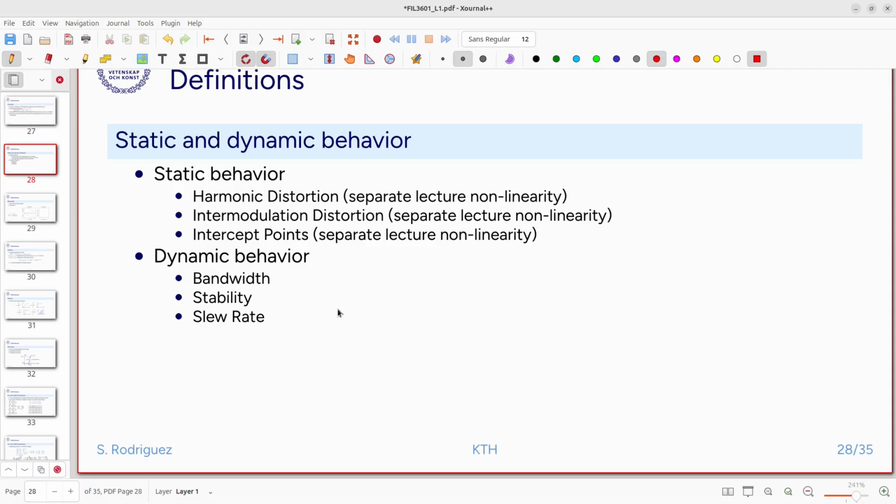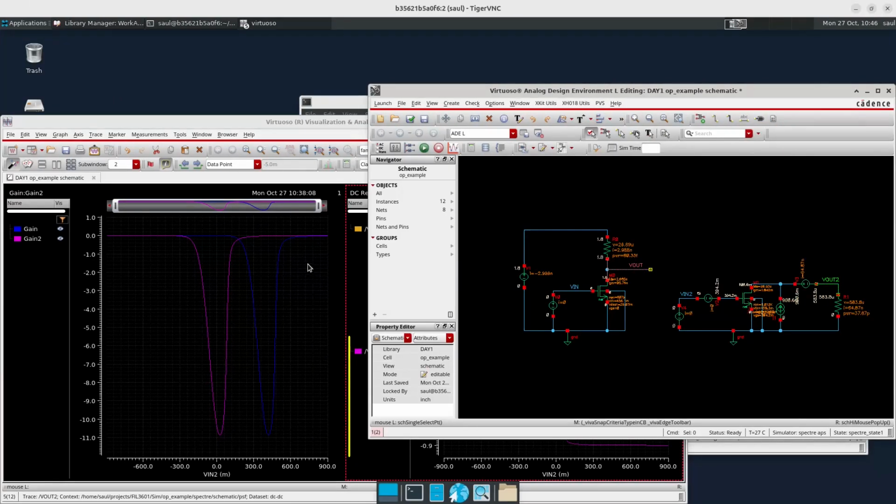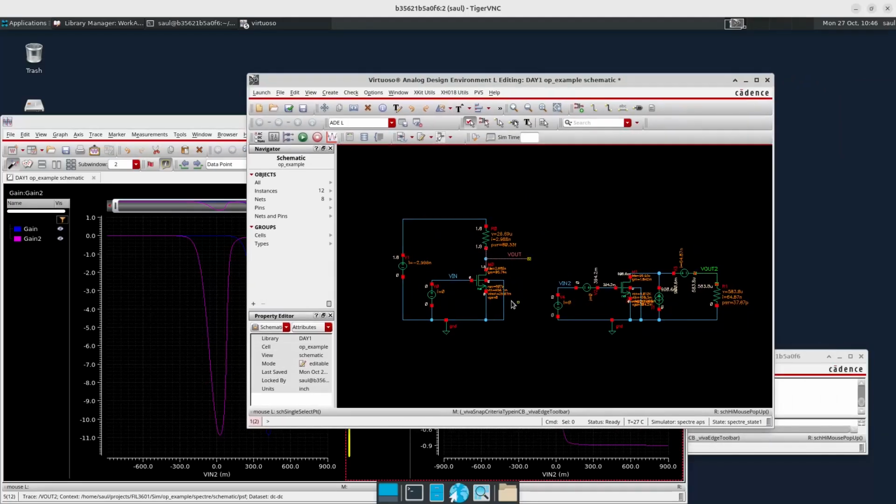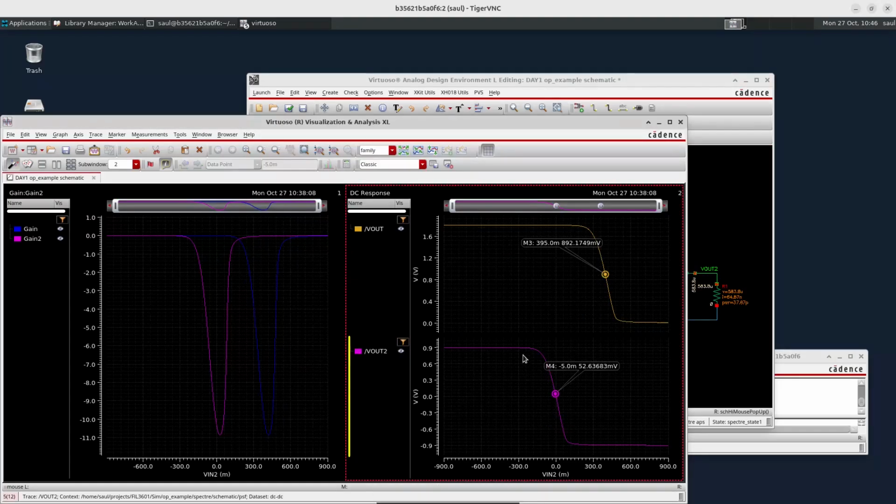Very quickly, if we see our amplifier, or circuit that we define as an amplifier here, we have an input voltage at the gate and output at the drain. It is going to have a transfer function, as we saw here. This is a function of the output versus the input. If we differentiate the output, we will get the gain of the amplifier, the differential gain.